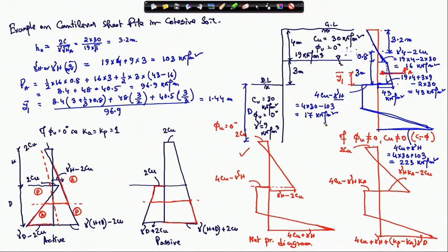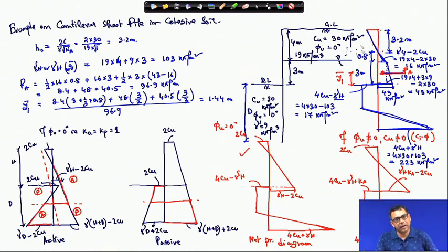Okay. So, now there are a few points. First point is that, depending upon the Cu, in the upper portion above the dredge level, the total stress can be negative. That means, if Cu value is very high, H0 can be greater than 7 meter also. So, if H0 value is greater than 7 meter, in the upper portion we do not need to consider any stress, because we will not consider the negative one.